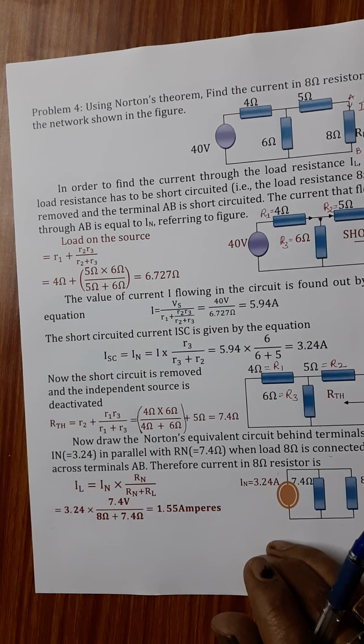The new, simpler circuit enables us to make rapid calculations of the voltage or current, and hence power, which the original circuit is able to deliver to the load. It also helps us to choose the best value of the load resistance or impedance required to accomplish the maximum transfer of power.